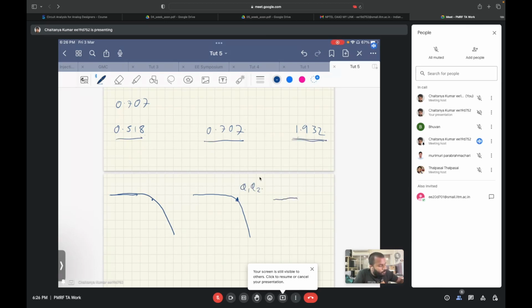So over here, when 1.932 gets multiplied with these gains, it still won't be able to peak greater than 1. So in this case, you won't need to reduce the DC gain of the last biquad, or any biquad for that matter. You will get the maximum signal to noise ratio that can be possible. Do you get my point?